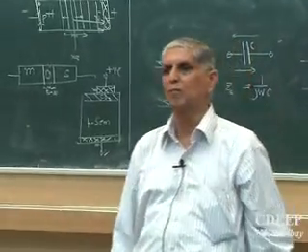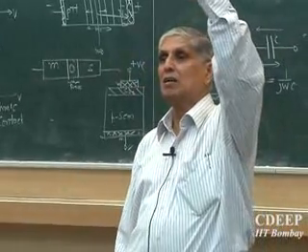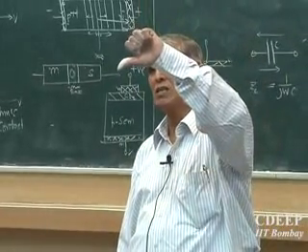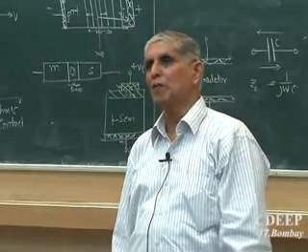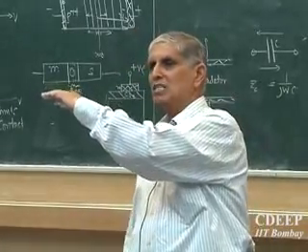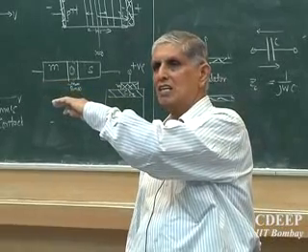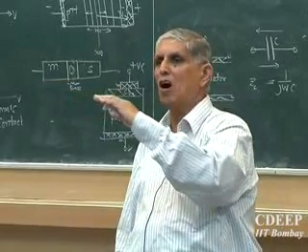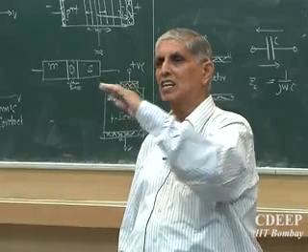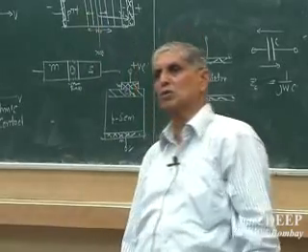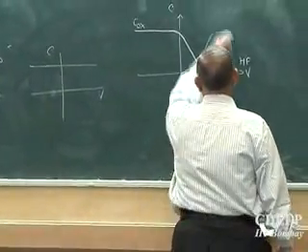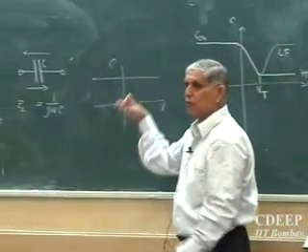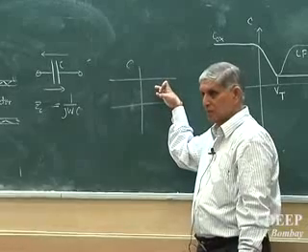The value at which the minimum is reached is called the threshold voltage of the capacitor, at which the capacitance becomes minimum. Either it may remain constant if the measurement frequency is higher, 1 megahertz and above, or if it is very low, 1 hertz to 10 hertz, it may climb back to its oxide value. Now this CV is different from this CV.